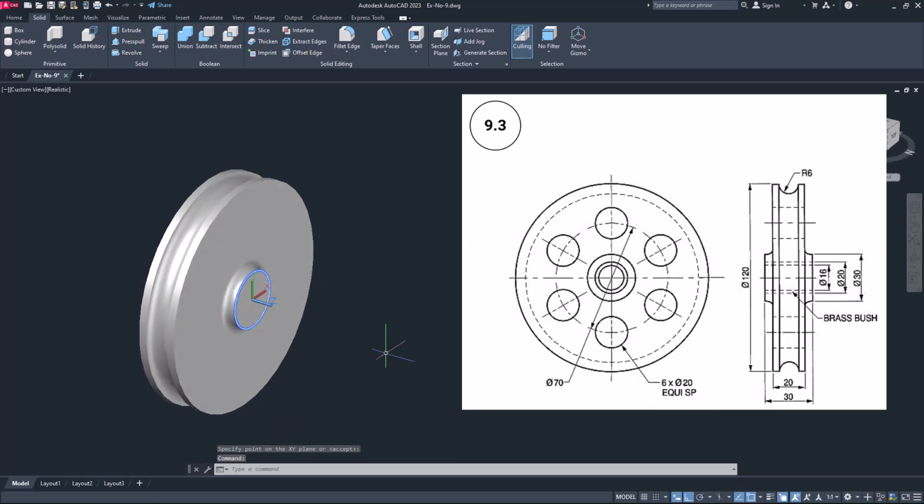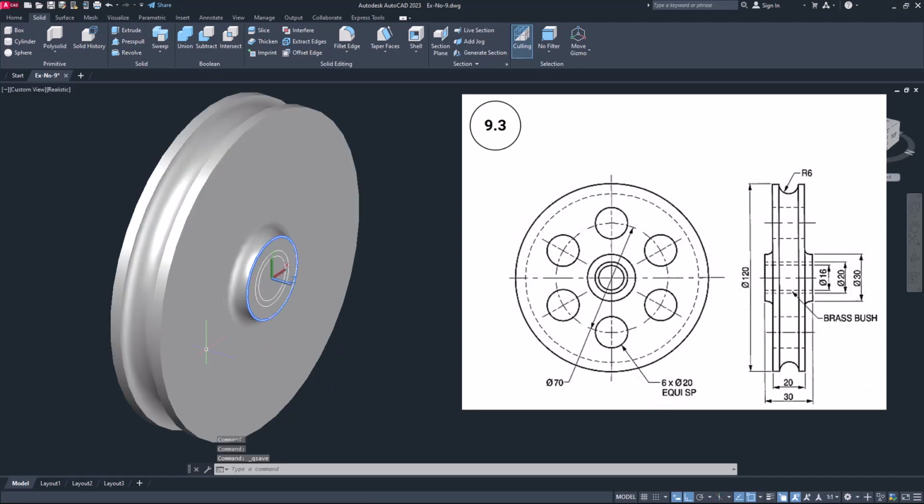Okay. Now let's choose the circle command. This time I am going to use the origin, that is 0,0, to place the center of the circle. Here I will choose the diameter option and type 20. Similarly, I will repeat the circle command. This time again 0,0, enter, diameter, D space. This time it is 16 mm. Okay, now let's save.